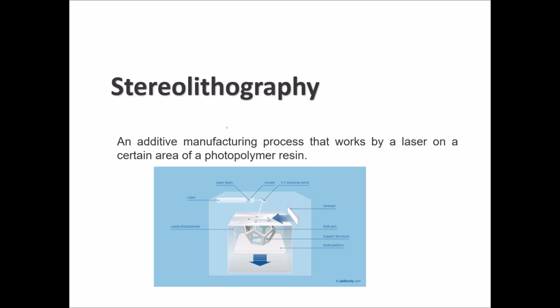So the laser comes in here on the liquid. The points where the laser is projected are carefully programmed to replicate the needed design. It takes layer by layer based on your 3D design and your slicing process. The laser is projected layer by layer, and after the laser is projected on the liquid photopolymer, the liquid photopolymer will solidify. It will move from the liquid state to the solid state. There are some powders or particles at that moment,